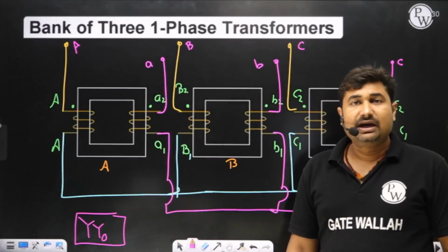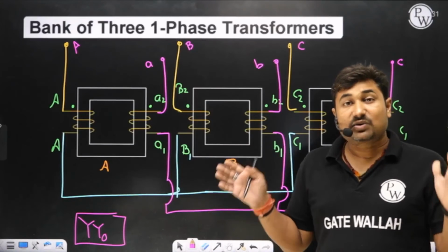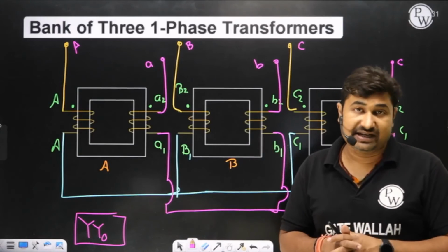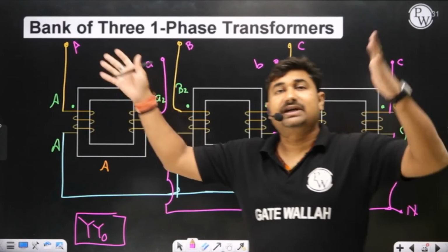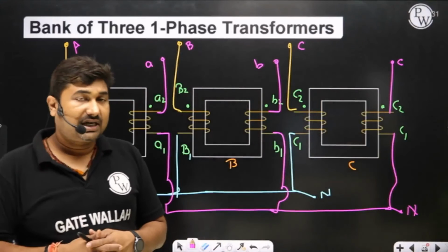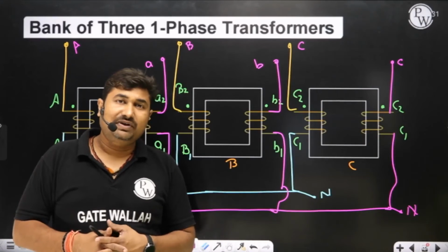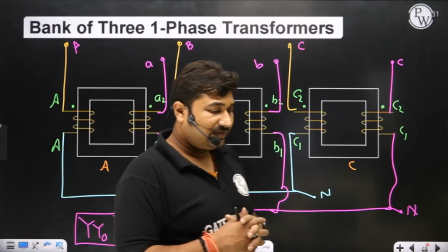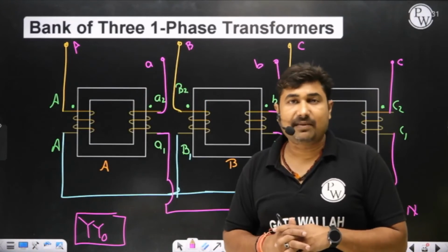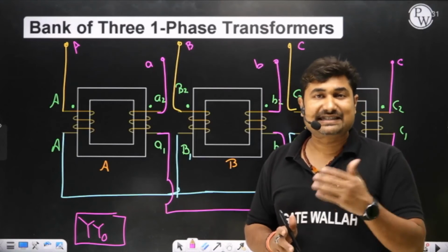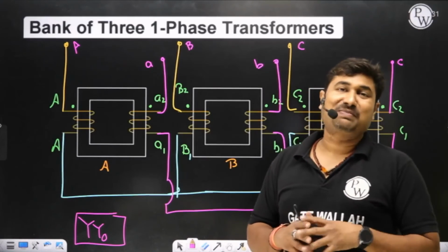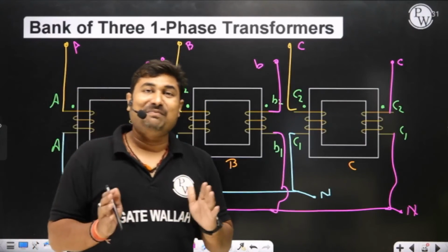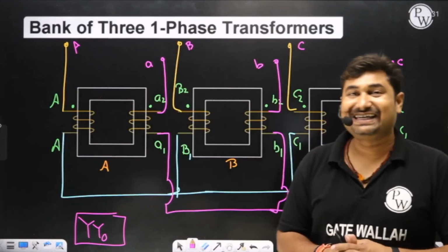One more thing, a single unit is quite difficult to transport, especially in hilly areas, because the size of the transformer itself is bigger than the trucks. It is quite difficult to fix them in hilly areas, and hilly areas are where the base generating stations are. So all the power is coming from the base power plant. Maximum portion of the power is coming from the base power plant. There we need maximum rating transformers. Is it okay? Yes, sir.